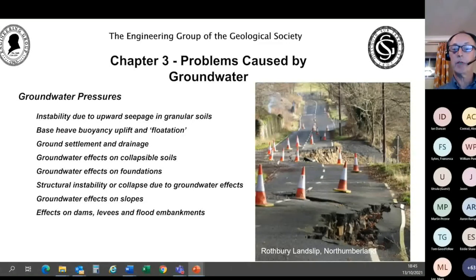The failure mechanism was related to increased pore water pressures and reduced effective stress following heavy rainfall. Despite small movements over the preceding years, nothing very much was done to address the problem, except resurfacing the road to cover over the cracks. That was until the major slides happened.